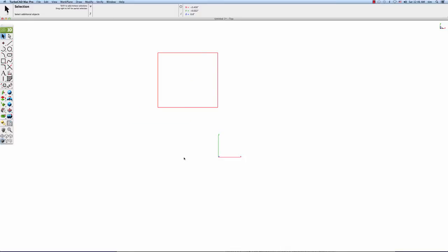And now when we select our object, when we hit the arrow keys, it's actually moving the object 1/10 of an inch at a time. If you hold down the shift key, it will do it 10 times whatever your nudge distance is. So in this case, it'll do it 1 inch. So that's how you can change the behavior of the arrow keys to nudging an object, is if you just change it to a non-zero value.